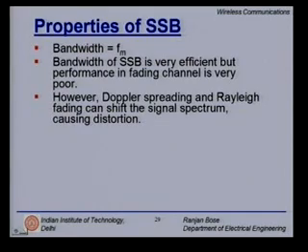Doppler spreading and Rayleigh fading can shift the signal spectrum, thus causing major distortions. Please picture the SSB in the frequency domain. Any shift because of the Doppler frequency shift will cause a distortion at the demodulator side.